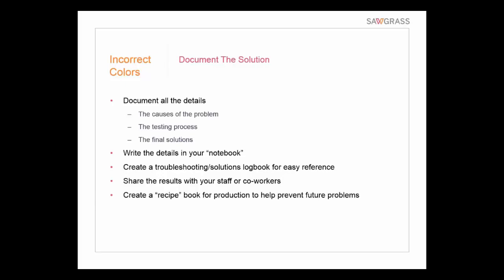So going back to incorrect colors, if the incorrect colors are occurring, stop and say, did something change? Okay, that's your starting point, because I can tell you a lot. New substrate, color problem. Okay, it's probably the substrate. I mean, as simple as that, it's probably the substrate. But you can certainly look then, am I using the right pressing parameters for that substrate? If it occurs in the middle of a job and nothing had changed, and all of a sudden you start seeing issues like that, that may be going back to the heat press.